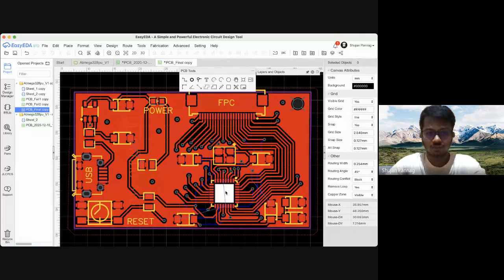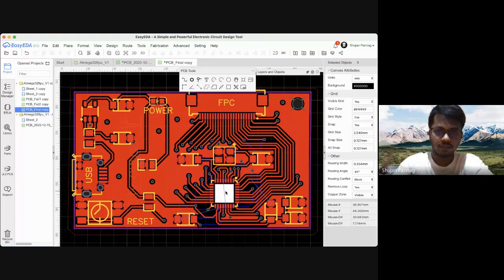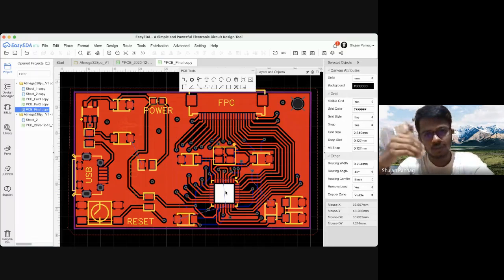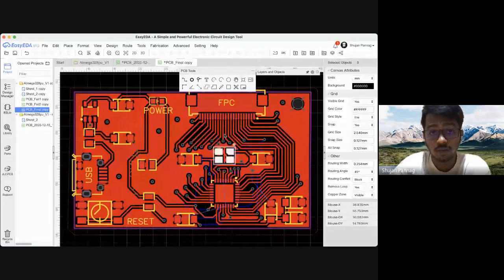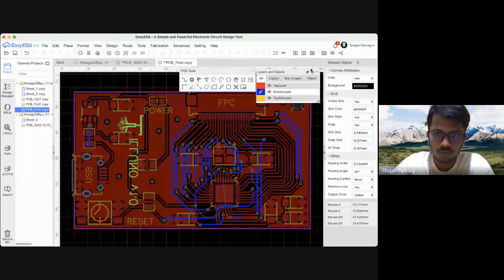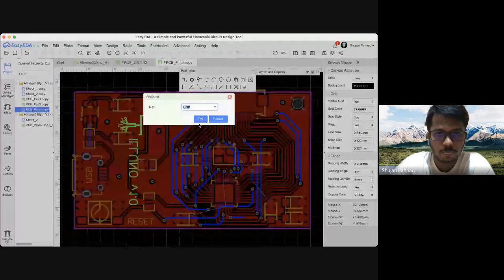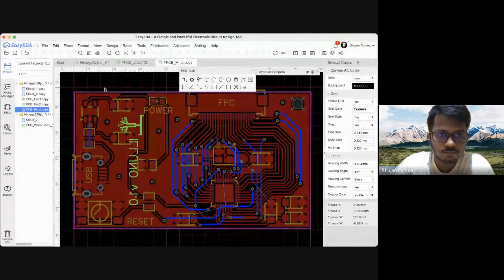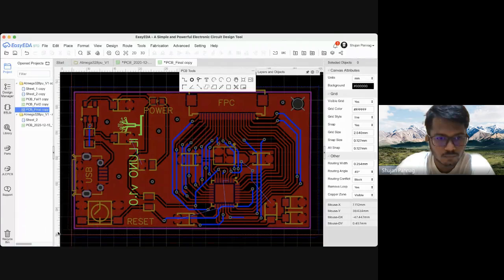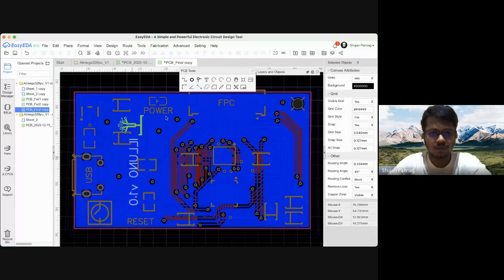That is because, while showing the other circuit I showed you, the ground and the VCC are in alternating positions. It's really impossible even to route them on the top layer. So I wanted another ground layer. If you want another layer at some point, you just hit bottom, because we just have to create another copper fill, which is also a ground, and hit escape. Now it fills with ground on the bottom as well.